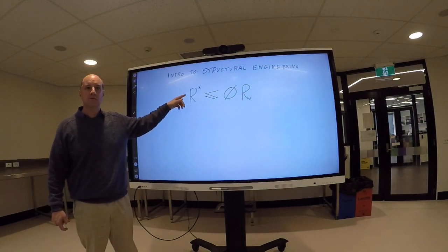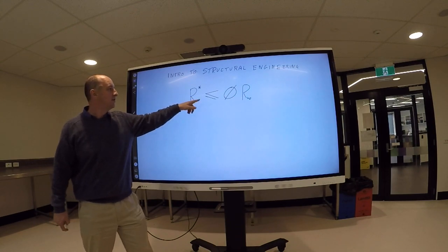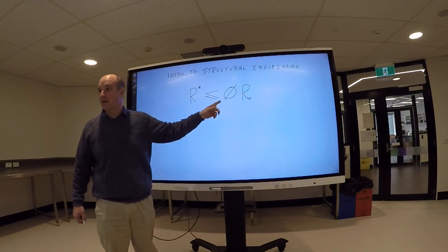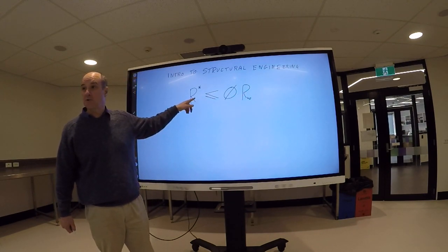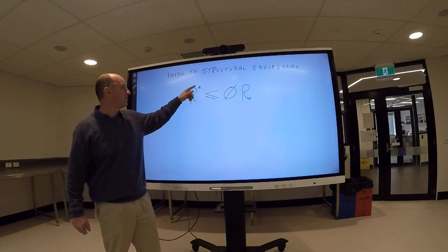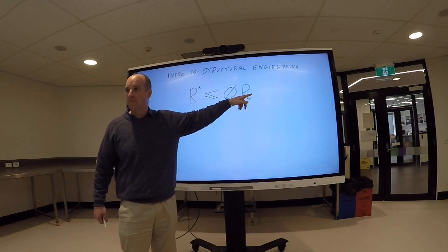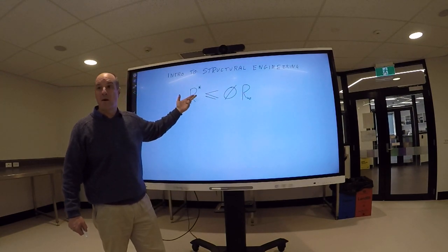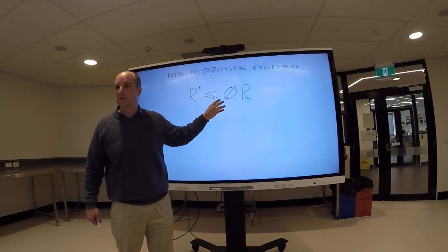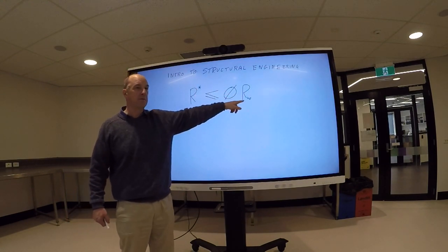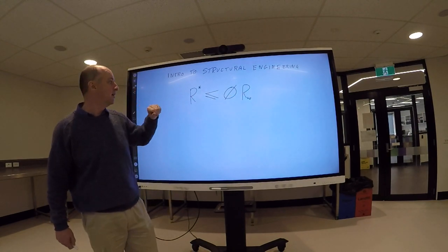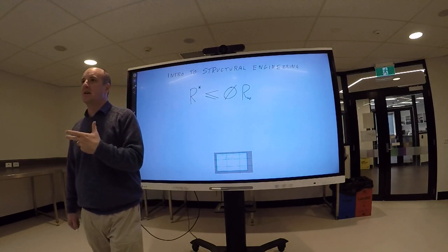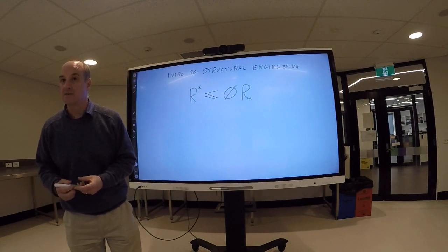Whenever we have a force, we have what we call an action. We have anything that's got the capacity to resist that particular action, okay? There's a bunch of different kinds of forces, so you'll see like F star is less than phi R U naught. It might be M for moments, might be V for shear forces, whatever the action and the applicable capacity to resist the action, okay? The R U naught is our capacity. The U naught means the ultimate capacity of that thing, okay?